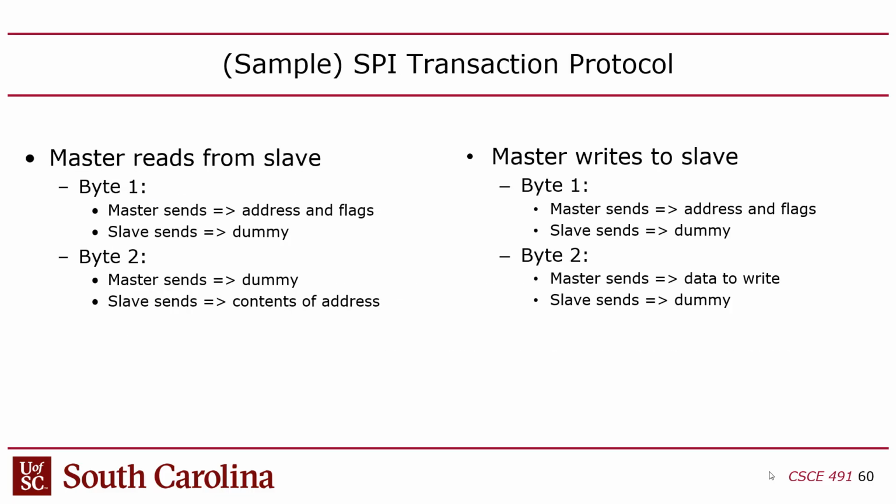And when I say programmed I/O, what I really mean by that? Programmed I/O is defined as having an address. It's an addressable transaction. When I was a kid, they used to call it a coordinate addressable memory, meaning that there's an address and then there's data. SPI, the protocol of SPI doesn't really have a concept of an address at all. So the transaction protocol is built on top of this exchange protocol.